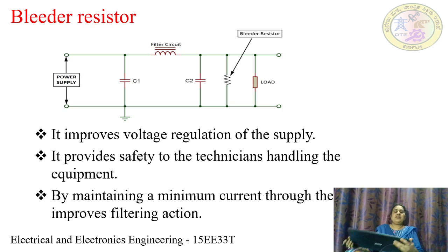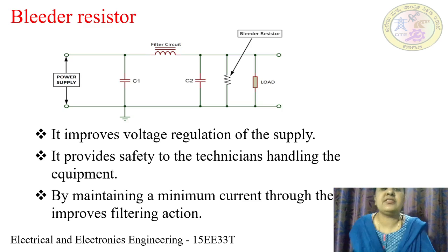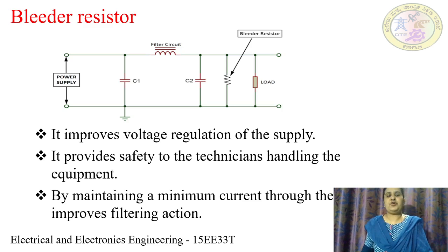So we are talking of the ripples, okay, we talked about ripple factors. Then we talked about the different configurations: the series inductor filter, the shunt capacitor or parallel capacitor filter, and the choke input or LC filter. The pi filter is the widely used filter.